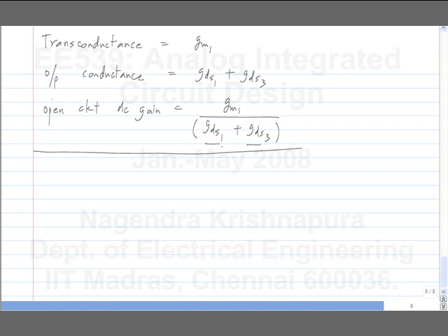Probably not. If you have not simulated any circuits at all in that particular technology, it's hard to do. And generally calculations of lambda, etc., if you look at it, lambda is not even given, right? It's hidden in many parameters. But usually what happens is you will start playing with some technology. Let's say you make an inverter out of minimum size transistors. If you plot it, you know what its slope is, so you roughly have an idea of the GM by GDS of the minimum length transistor.